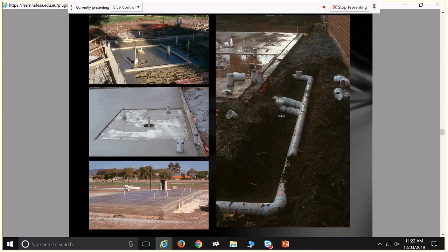If you're doing a bathroom that's 4 metres, like this is a large bathroom, right? If we've got 4 metres distance, and you're planning to have your shower as your draining point, which is right in one corner, you've got to have 50 millimetres of height difference from one side to the other. You need to know that for specifying how much to set your slab down, because that slab set down dictates how much screed you can then put in that floor to produce that slope.